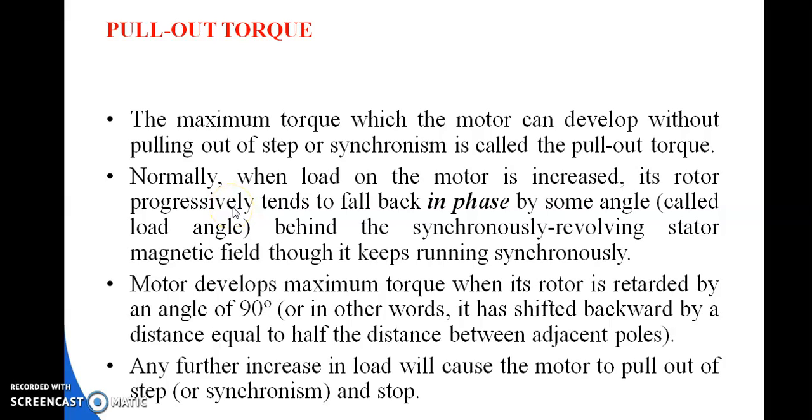Next one is your pull-out torque. The maximum torque which the motor can develop without pulling out of step, or without losing its synchronism, is called the pull-out torque. Normally, when load on the motor is increased, its rotor progressively tends to fall back in phase by some angle called the load angle behind the synchronously revolving stator magnetic field, though it keeps running synchronously.